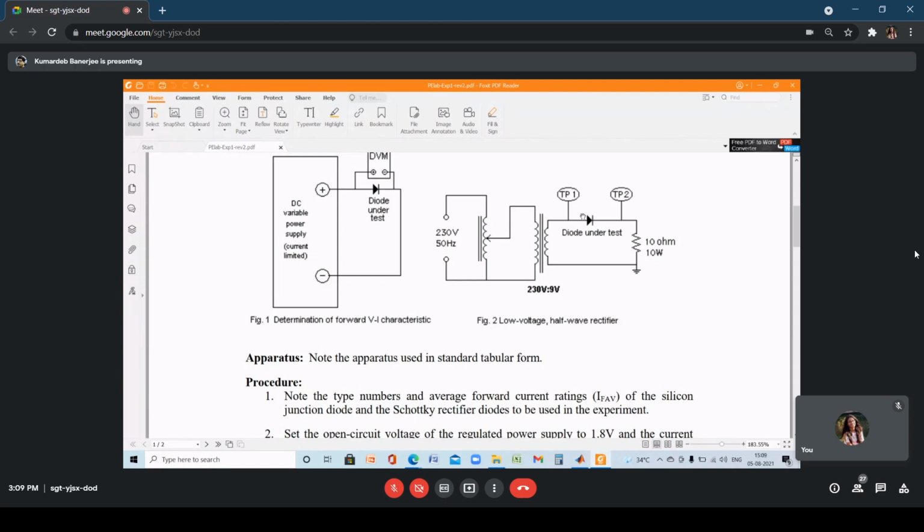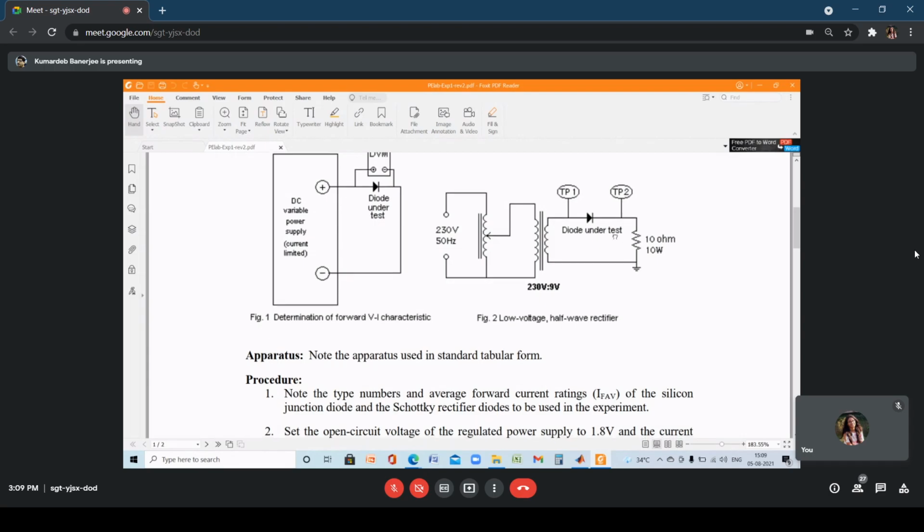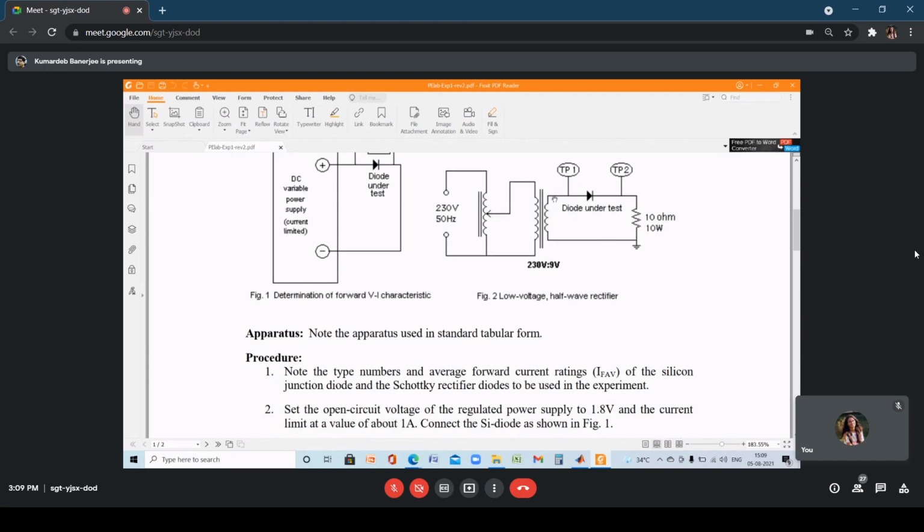Okay, so that means there is a transformer, and you have connected the half-wave rectifier circuitry in the secondary winding of the transformer. So the input, if you measure it by using a simple analog two-channel oscilloscope, these are the test points at which we are taking measurements. One is TP1 and the second is TP2. And we are measuring both the voltages with respect to ground, some defined circuit ground.